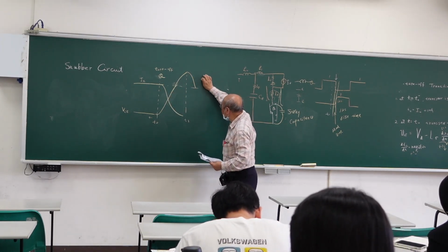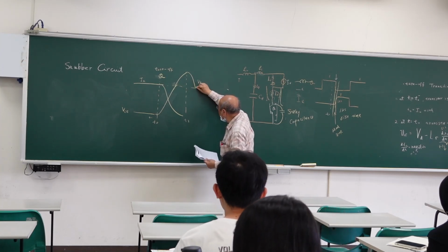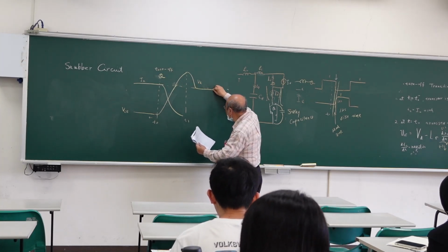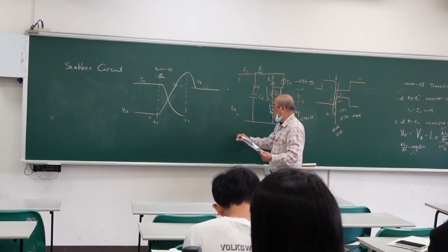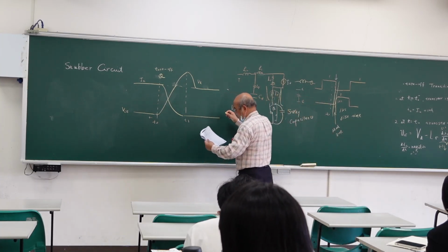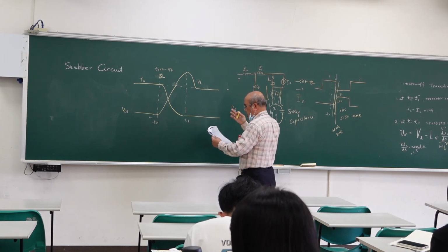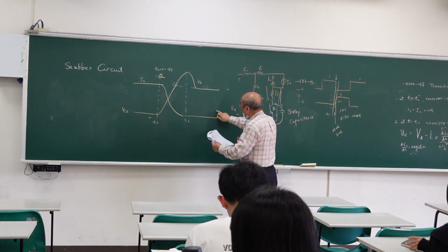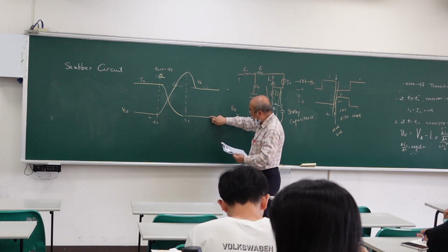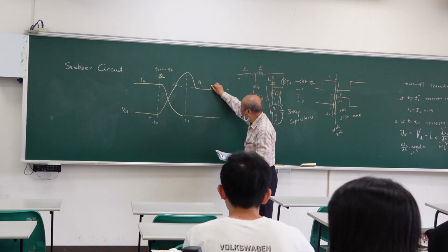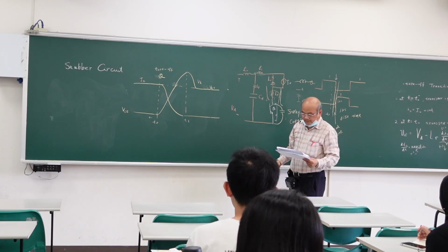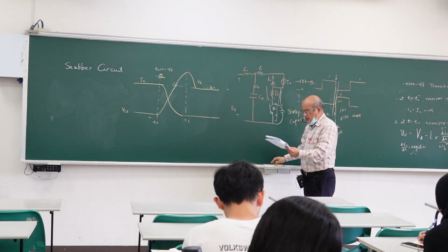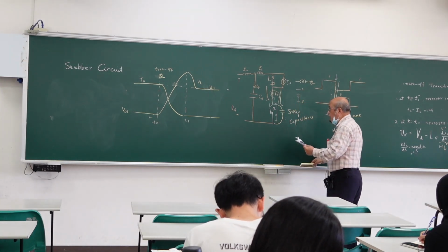Okay. So if you design a snubber, then it is good. Then it will start here. Okay. So we start here. Now the Q turns off. If Q turns off, the current becomes 0 and the voltage becomes VDC in steady state, right? Okay. So this is the turn off time.